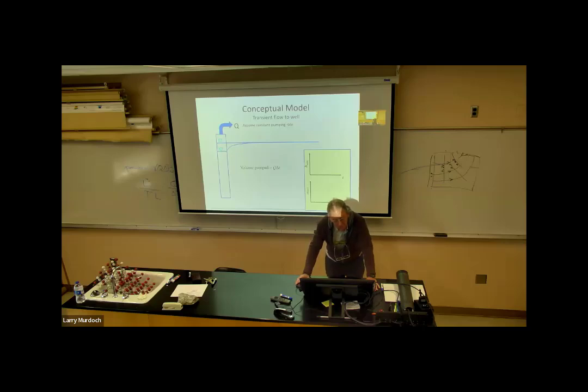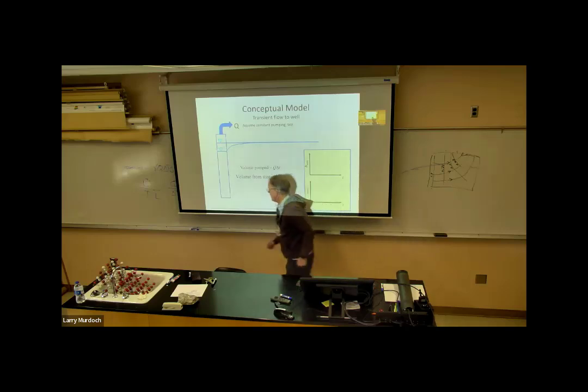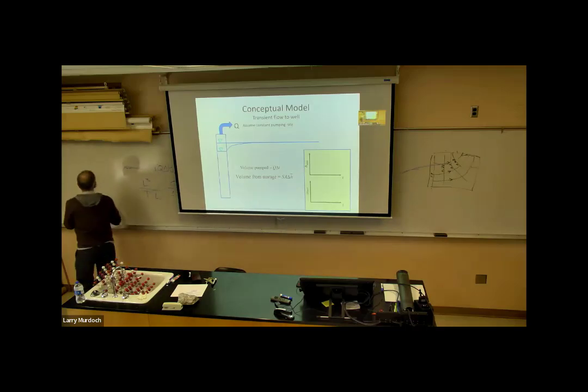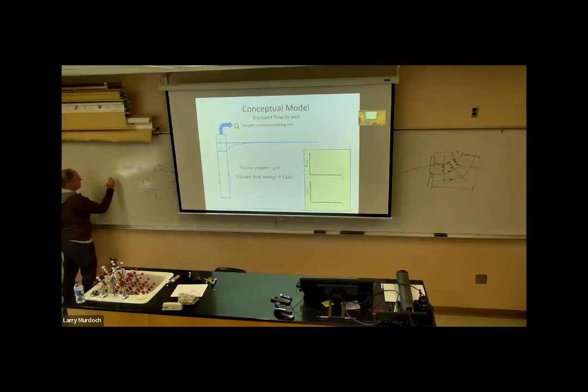Here, with this pump, we're dropping the head and we're moving water from storage, and the specific storage or the storativity could be what tells us what happened. So the volume that is released from storage, remember, we said that the storativity is equal to the volume released from storage per area per change in head, right? So for the volume released from storage, we can bring this stuff over here, and that's what I did.